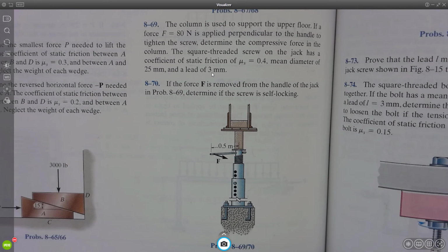Okay? All right, so go ahead and do this. You got this. This is a pretty straightforward one. First, you can check, is this self-locking? I guess it actually doesn't matter. If you're asked to figure out how much it smashes, if you're making it worse, it doesn't matter if it's locking or self-locking, it doesn't make any difference. You're adding the two angles, the friction angle and the angle of the ramp, okay?